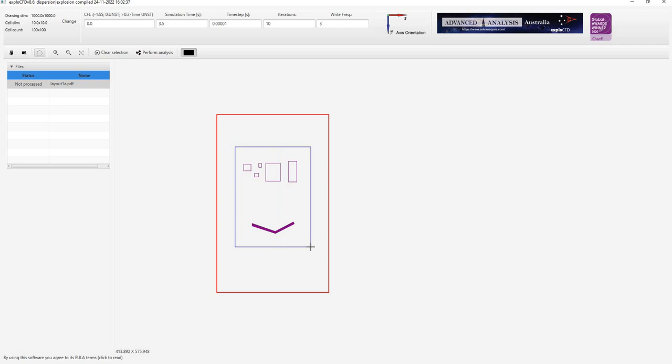Obviously, we do want them to be there. We've got a few buildings and a large blast wall. So I'm going to select a smaller rectangle within the red rectangle, again top left to bottom right, by holding down the right mouse button and then releasing. Everything goes red. Right click again and go include selected lines. So now these lines will be treated as walls. You've got a few buildings here and a very large V-shaped blast wall.